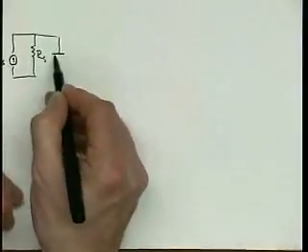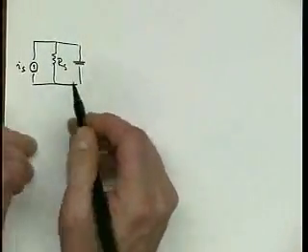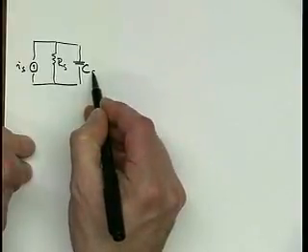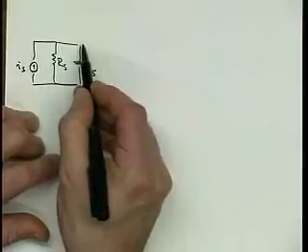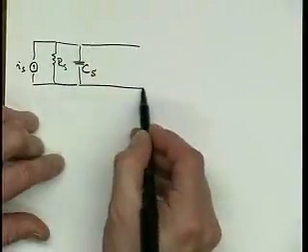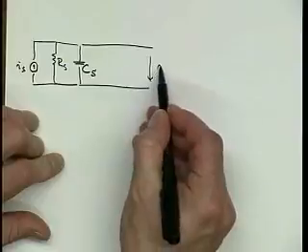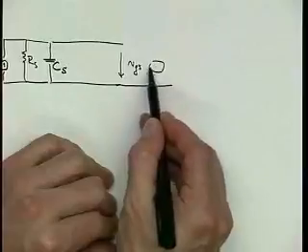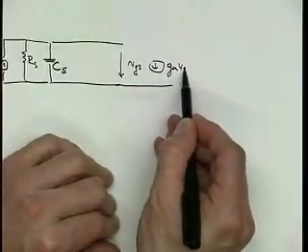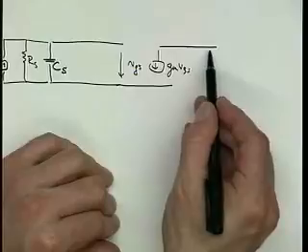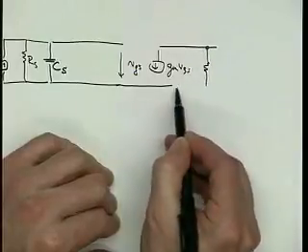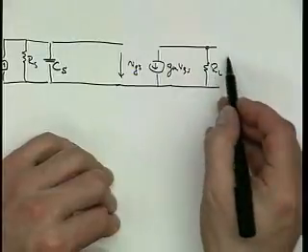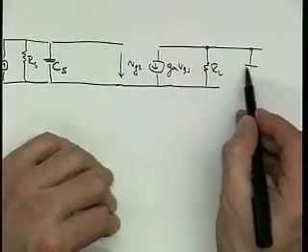It has a capacitance, CS, and that is applied to our MOS transistor, where it produces a VGS on its gate. Then we have the transconductor gm·VGS. Then at the output, we are going to have RL, and we also have CL here.